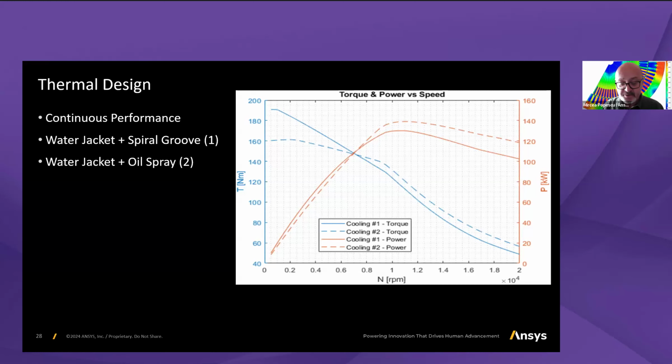In this case it was insulation class 180 degrees Celsius, or H. And for the rotor bars, we assume the same maximum temperature, 180 degrees Celsius. Additionally, in induction machine, I mentioned earlier, bearings are critical from the potential fault point of view, and the temperature of the bearings as well had to be maintained below 120 degrees Celsius. So with these three components in place, together with electromagnetic, considering as well the mechanical noise and vibration, from the thermal point of view, we can compare the two cooling systems.